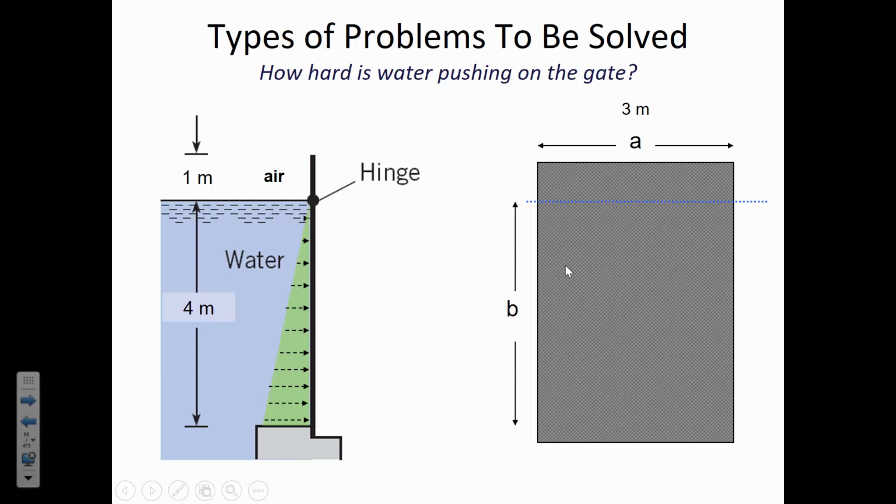So the units of gamma are newton per meter cubed, because if we look at what gamma is, from the hydrostatic equation we said delta P is delta H times gamma. So gamma is delta P divided by delta H. So it is how much the pressure increases per unit of depth that we go downward.